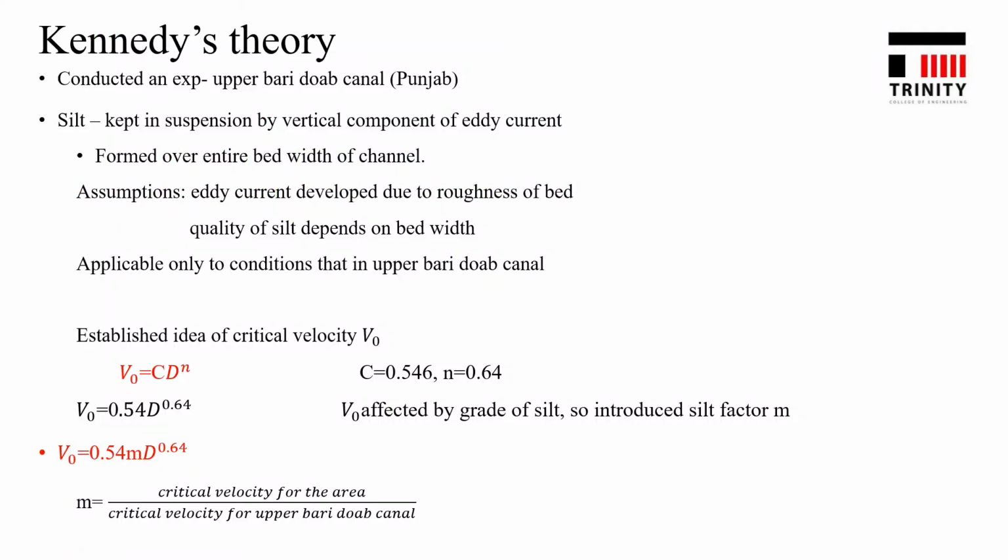Kennedy conducted an experiment in the Upper Bari Doab Canal, which is situated in Punjab. He states that the silt carried by flowing water in a channel is kept in suspension by the vertical component of eddy current, which is formed over the entire bed width of the channel, and suspended silt rises up gently towards the surface.